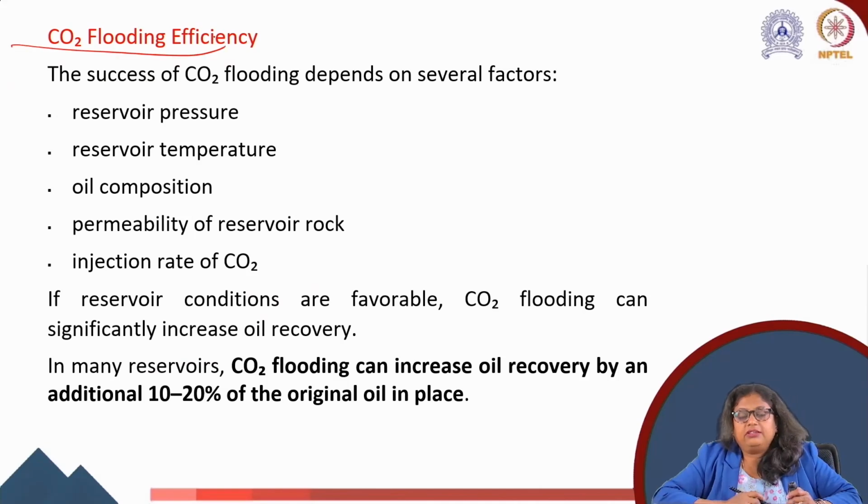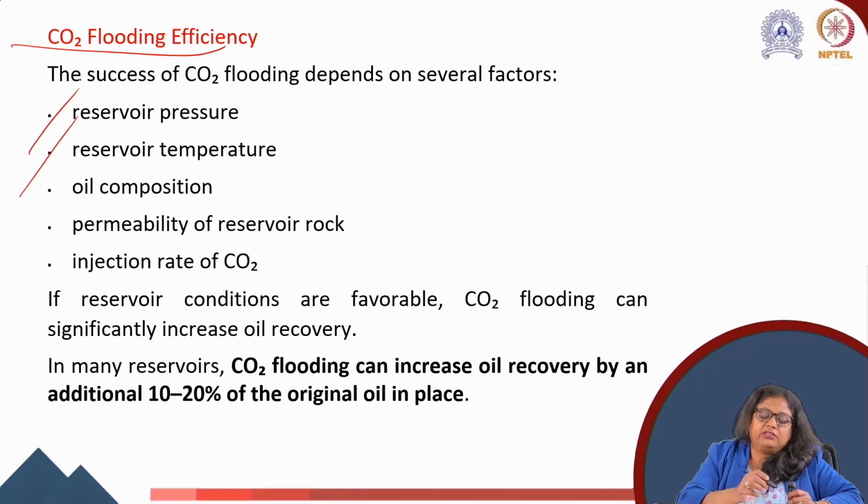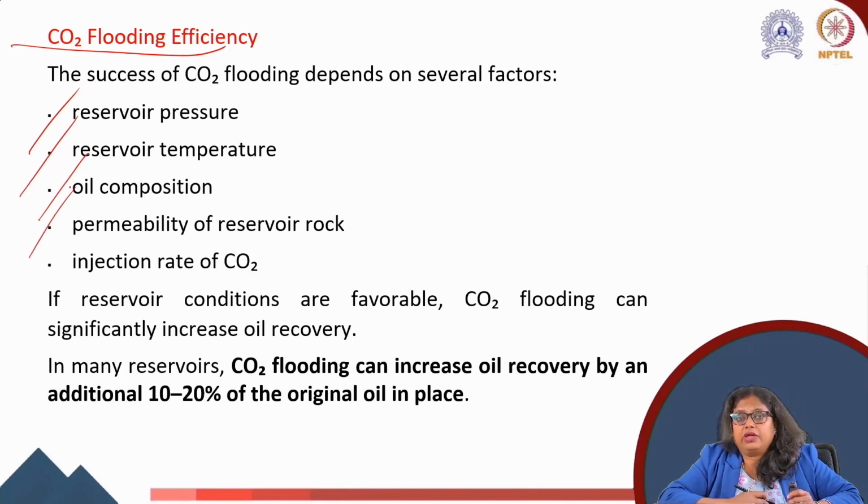Now let's see CO2 flooding efficiency. The success of a CO2 flooding depends on several factors: reservoir pressure, reservoir temperature, oil composition, permeability of your reservoir rock, and injection rate of CO2. The efficiency of the CO2 flooding depends on these parameters.